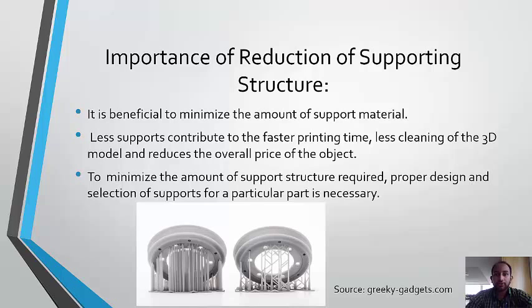Importance of reduction of supporting structure. It is beneficial to minimize the amount of support material. Less supports contribute to faster printing time, less cleaning of the 3D model, and reduce the overall price of the object. To minimize the amount of support structures required, proper design and selection of supports for a particular part is necessary.